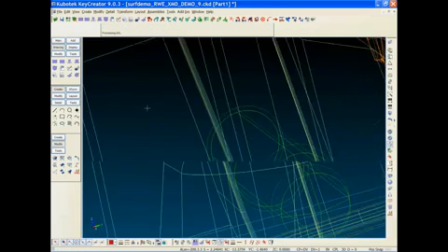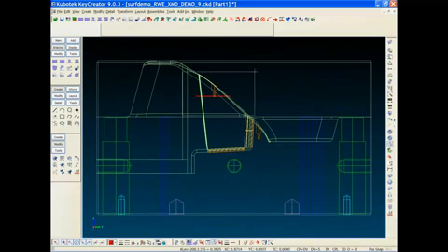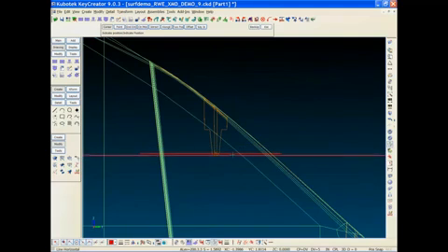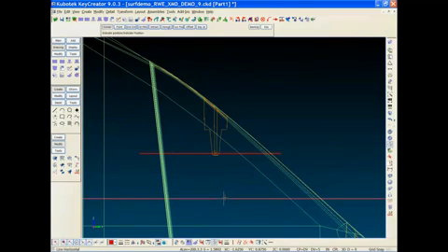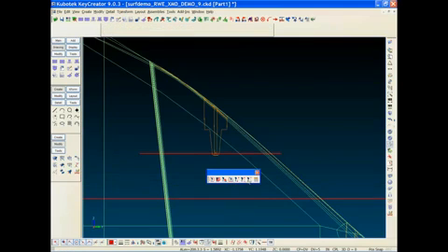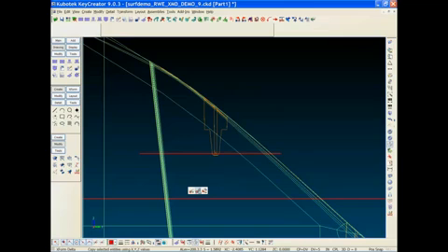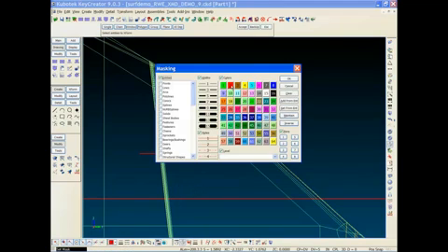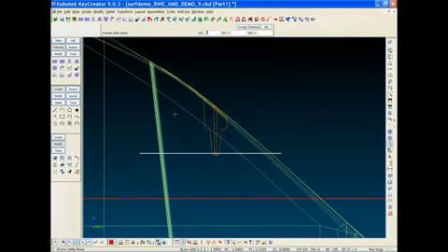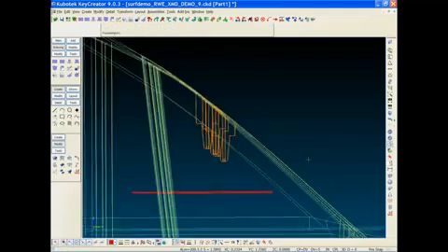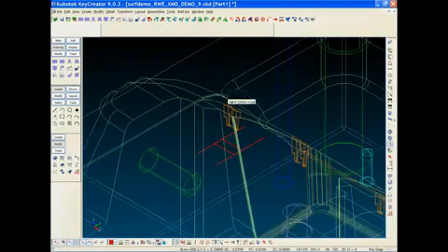So I'm going to do a quick switch to the long section, and I need a little bit of steel underneath the bottom of the part to accommodate my screw. So another construction line, and I'm just going to move those lines that I created down the distance to establish the bottom of my insert, the bottom of the insert pocket, if you will. Alright, so I've got that depth established.